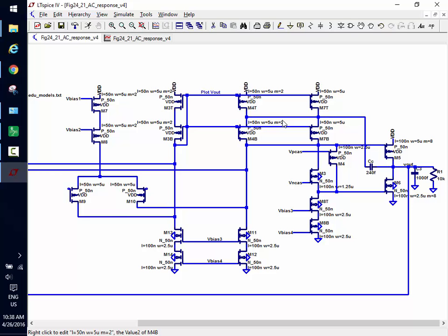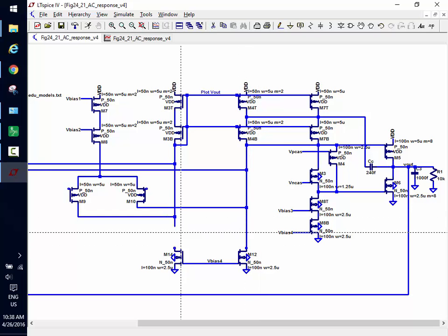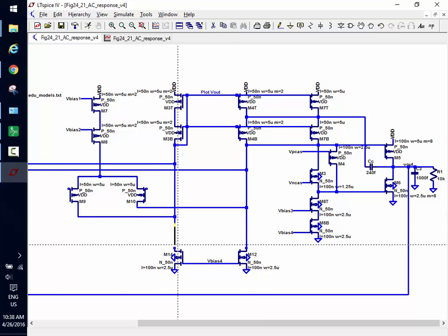That just means that if these shut off over here, there'll still be some current that can flow over here. I'm going to make this simpler, because it doesn't matter. Let's get rid of these. Let's go ahead and put from here down, yes. So even though the NMOSs are turned off, just by widening up the PMOS, there is going to be room for that current to flow because of the widening.